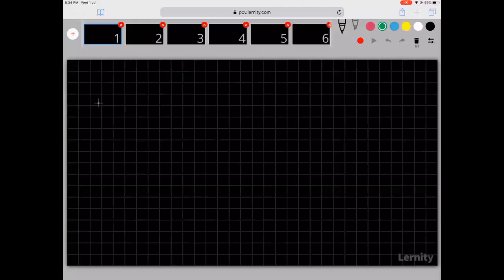Ohms, this is 3 ohms. Suppose this is 10 volts. Now 10 volts is the potential difference between the two ends. That means from the negative to the positive, the potential difference is 10 volts. So suppose this side is 0, this side will be 10. Suppose this side is -5, this side will be +5, because the difference between them is 10.